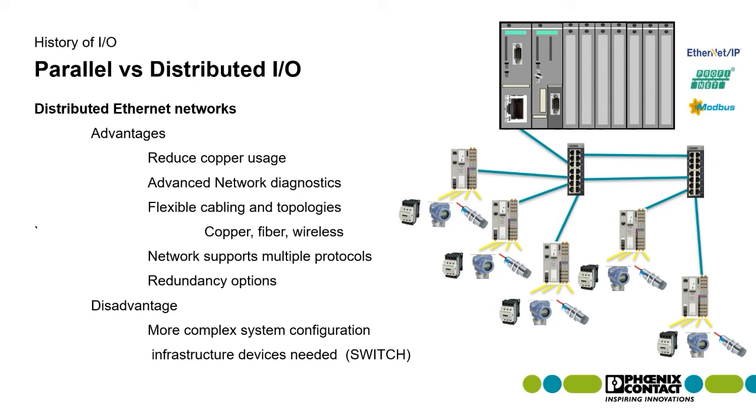In your home network, like what I'm doing now with my test network, it's all hooked together into one big network because it doesn't really matter. But in a real world application, you would keep all those separate. But in the end, your Ethernet network in your office is the same as your Ethernet network on the plant floor. It's Ethernet. It's just the devices you use. A switch for the industrial plant floors has a whole set of different ratings and compatibilities versus the router in the office. That one can't handle the extreme temperature conditions and the robust environments that you're going to see on your plant floor. So there's a difference in the components, but in the end, it's a switch. It's Ethernet.